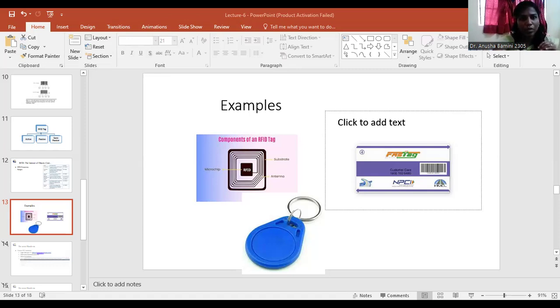These are some components of SCADA: human machine interface, remote terminal unit, programmable logic controller, and distributed control system. These are the utility automation components available in SCADA. Using these components, we can get the environment details and easily take a decision. And this is the middleware-based SCADA system. The middleware layers are hardware and protocol stack. Then over the middleware, there is the service and application manager and the application layer.